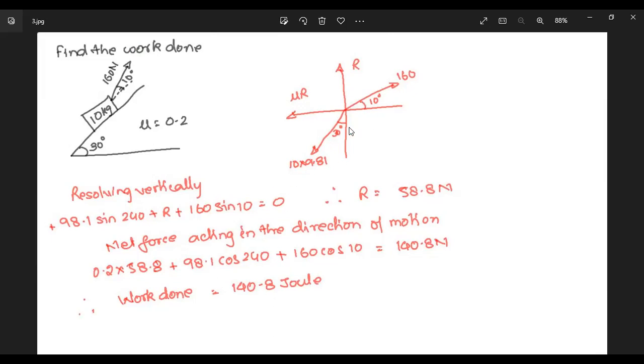So if you draw the free body diagram, either you can take it on a flat plane and then rotate, because it has gone in anti-clockwise direction 30 degrees. If you rotate this mass by 30 degrees in clockwise direction, it becomes as if it has been located on a flat plane. Then you can draw the free body diagram. There are two ways of doing it. Mg acts perfectly vertically downwards, and the forces are managed accordingly. The other way is you incline the weight itself and manage the forces accordingly.